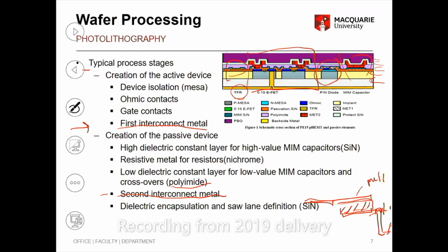And so this is how you build up each of the components. Now you don't have to worry about how you build up all the layers. You just have to follow the PDK rules. That's it. When you pick a capacitor from the PDK, it follows all the rules. When you connect, say in your circuit, a capacitor to an inductor, you have to route with metal one, or a thick metal. The other thing is about thick metal. I don't know whether I mentioned. You have a metal one in one layer, then a metal two in another layer.